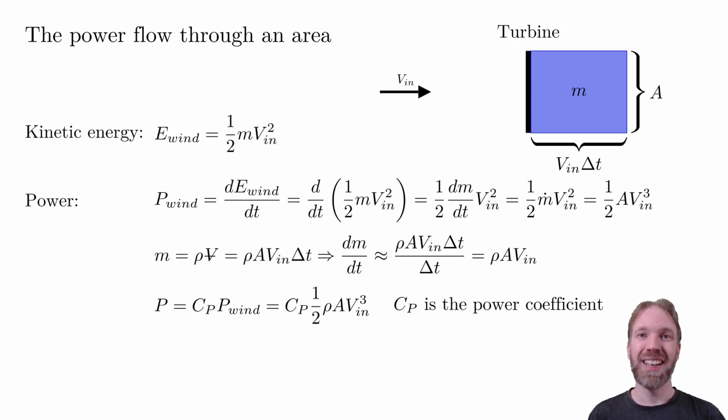However, for the wind, some of the kinetic energy will be left behind the turbine, and the flow can pass outside the turbine as well. In both these cases, another turbine could utilize this remaining energy, hence the energy is not lost as heat. The power coefficient is therefore easier to work with, as it does not care if the energy that the turbine cannot absorb becomes heat, or if it just remains as kinetic energy.